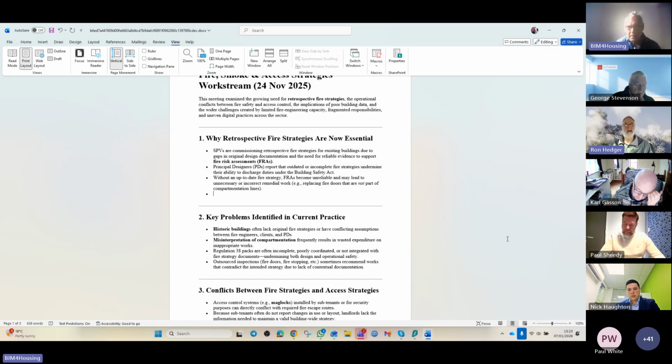Well, that can only be answered if you have a record of what was in place in the building, as opposed to what it has gradually evolved into now, without anyone being aware of it. So the fire strategy is the primary document on which all fire safety management sits, whether it is day-to-day management, or management of new build, alterations, change of use or upgrade. It's the base document on which the whole thing sits.